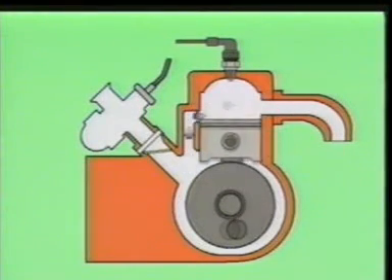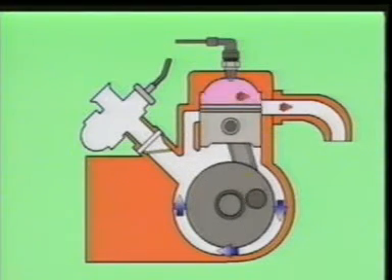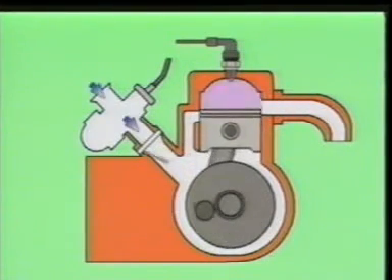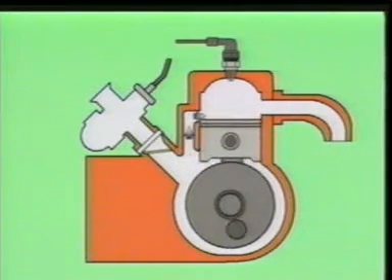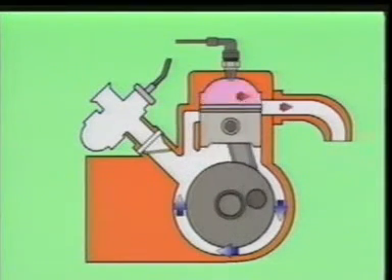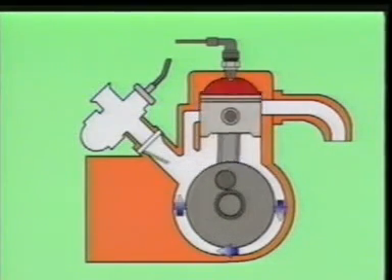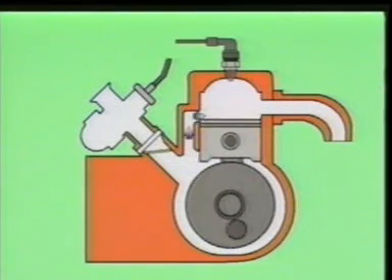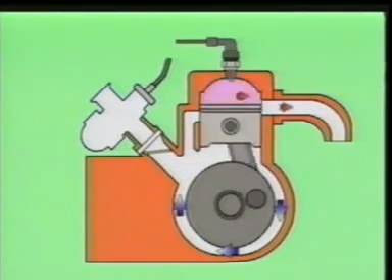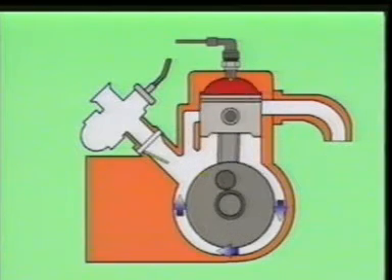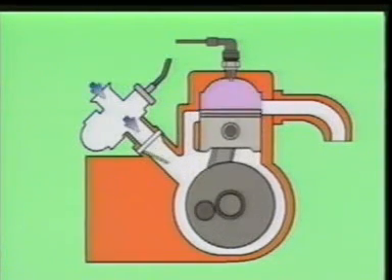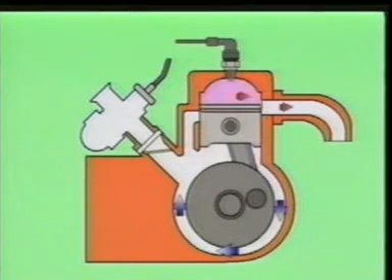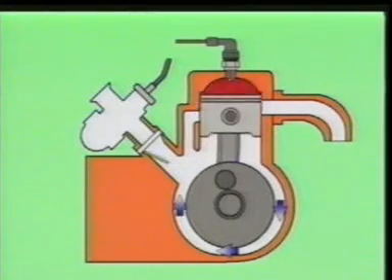In this way, the two-stroke engine completes one full cycle with 2 strokes of the piston, and power is obtained from every single revolution of the crankshaft. Mixture from the primary compression in the crankcase chamber is injected into the cylinder through the scavenger port, pushing out the exhaust gases. In order to achieve this effect as efficiently as possible, the position and angle of the scavenging port must be determined with extreme precision, taking into consideration how the engine will be used.